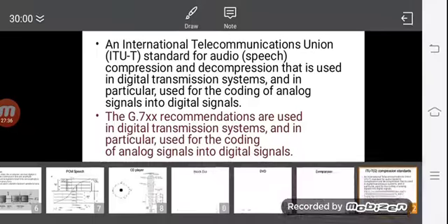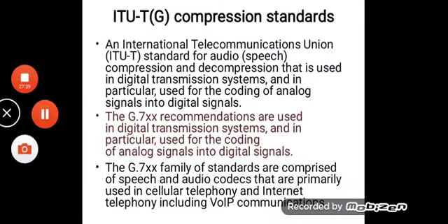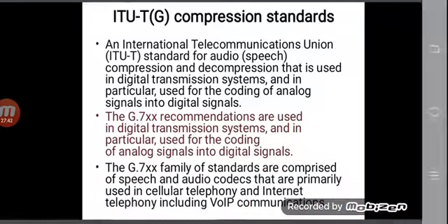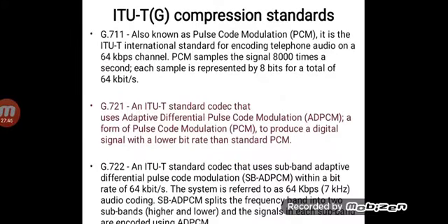Now there are a variety of standards available, out of which let us understand a few of the important ones here. The first standard, for the audio signal which is transmitted through the internet, is G.711, which suggests that for conversion of A to D, we need to go for pulse code modulation. When we go for this PCM, there has to be an analog signal for which we take 8,000 samples in a second.